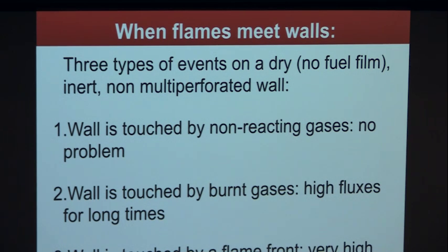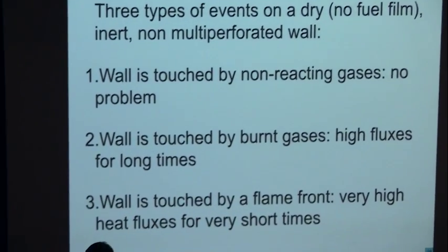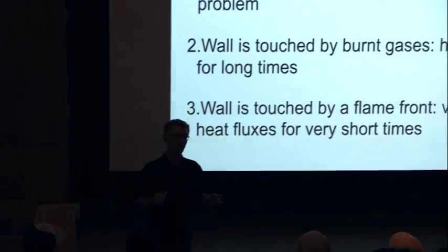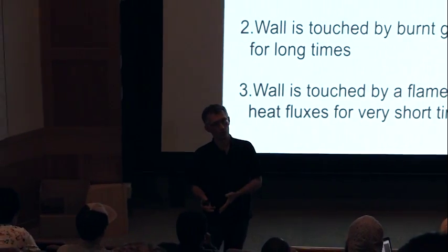The flames are going to propagate toward the wall, and there are many ways that things can happen. If you are here on the wall and the flame is down there and here you only have cold gases, you're fine. Okay? So if it's non-reacting gases, cold gases, you have no problem. Now, if unfortunately for some reason the burnt gases arrive where you are, it's a heat transfer problem only. It's hot gases on the cold wall.